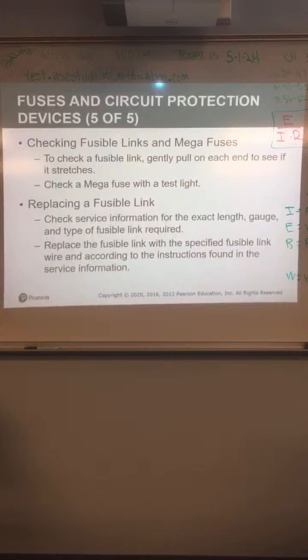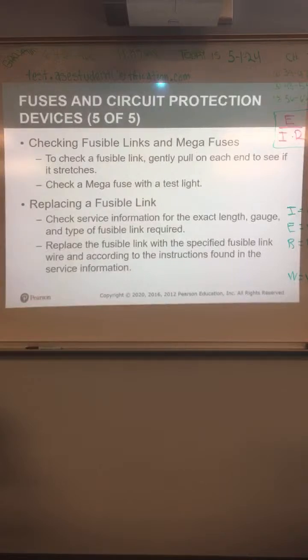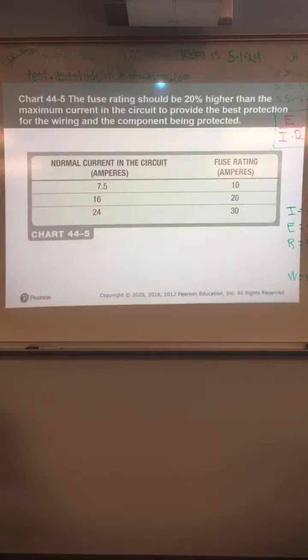Question. Off topic, but on topic. Mega fuses. It says one of them are HID headlights or 4 HID headlights. What does HID stand for? High intensity discharge. And they have an igniter that gets the process started. They're elaborate headlights. Gotcha. Replacing a fuse link, make sure you use the right stuff is all they're getting at. Again, your fuse rating should be 20% higher than the current that it's trying to protect.